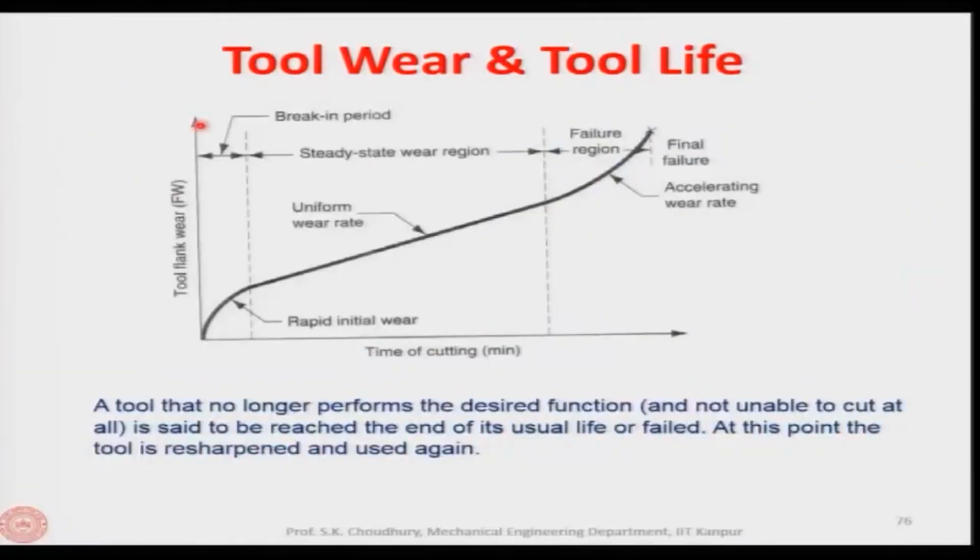Now, let us see how the flank wear progresses with the time of cutting. So, the curve goes like this. This is a popular curve, and it is explained in the following way: initially the tool is sharp, and there is a lot of stress concentration around the sharp tool. So, initially as it comes in contact with the workpiece, there is an initial break-in. This is called the break-in period.